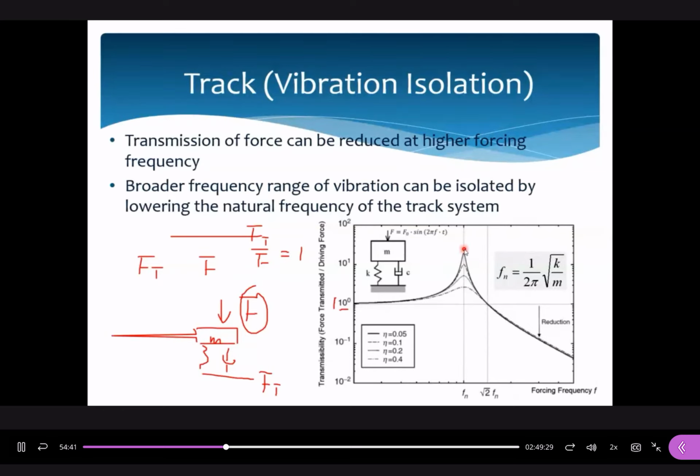Okay, P2 resonance, what is that? P2 resonance is a simple harmonic motion when the wheel sets and the wheels are working together in phase. They are vibrating in phase together on elastic support. Normally, it could happen at low frequency, 30 to 100 hertz.